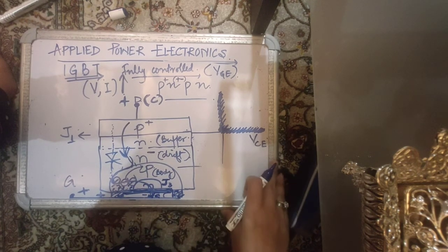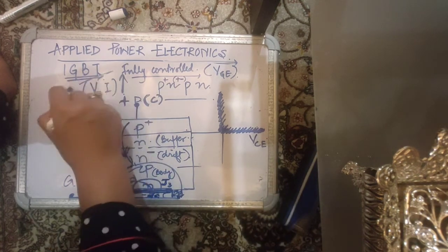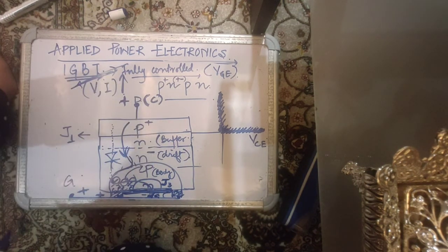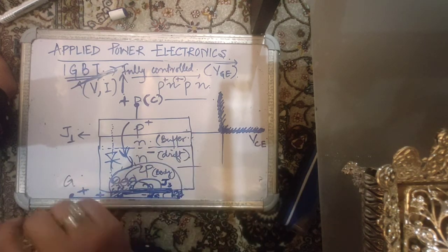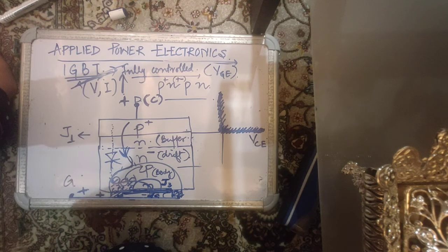So that is about your IGBT. I've briefly discussed these points. I've not gone into many details because I believe that this much is sufficient, that you know how it is a voltage control device and not a current control device, or how it can block positive voltages and carry only positive currents. Basically, understanding the basics of their operation.